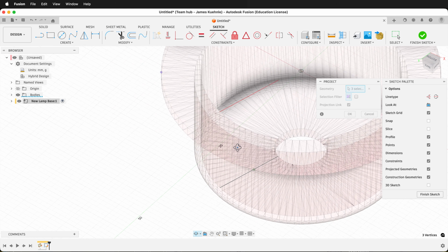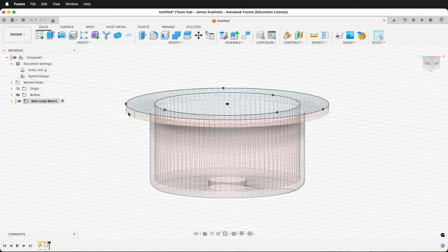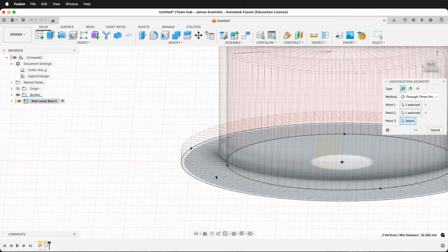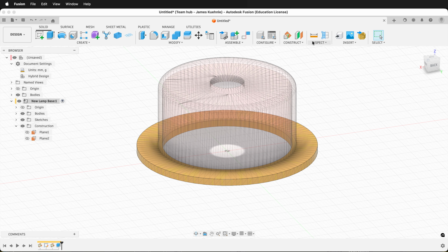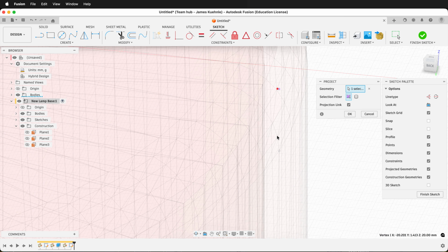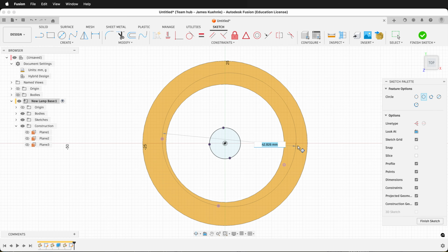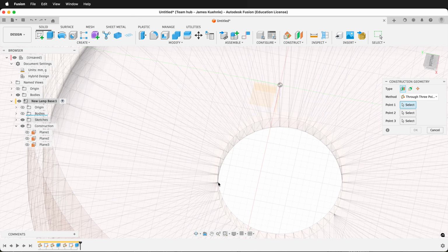There are, of course, commercial ways to do this in Autodesk Fusion with the Prismatic option, but that's not available on the hobby license. And even with that option, you still have to do a lot of manual reverse engineering. So this is going to take a simple STL file from MakerWorld and then reverse engineer it into a parametric CAD file inside Autodesk Fusion.